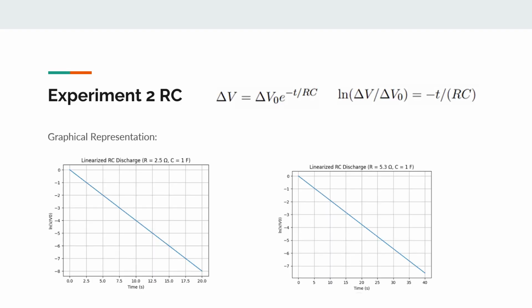Here we can see that the charging and discharging of a capacitor follows an exponential behavior, with the discharge process taking longer because it typically occurs through a resistor, which reduces the current flow compared to a direct connection to a source of power used for charging. When using a higher resistance bulb, the charging time significantly increases, which could be seen graphically using the above voltage difference formula rearranged to compute the time constant RC.